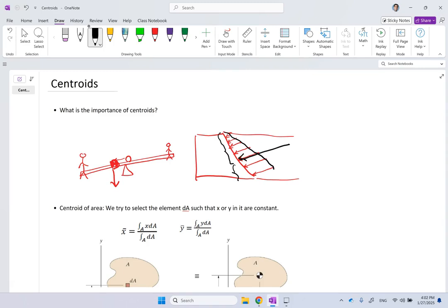Or even better, more advanced, if you look at the leg robots, if a leg robot is walking or moving, and you want to look at the static stability of it, by that I mean whether that robot is going to fall down or not. So let's say it has 3 legs or 6 legs or anything. So let's just say it's 6 legs. So if these are the contact points of these 6 legs of the robot, then when you connect them together, you're going to get a convex hull.